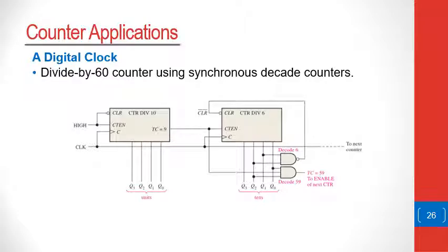One of the first components of this counter is the divide by 60 counter. You can see that the first counter is a counter with a modulus of 10, so it will count from 0 to 9. And now the second one, it's a mod 6 counter. The way it's made is that whenever it reaches a value of 6, it clears. So whenever it reaches this value of 6, it resets to 0, 0, so that the count can go.